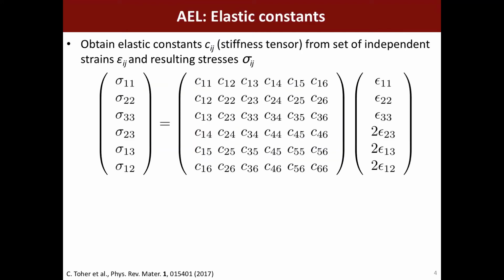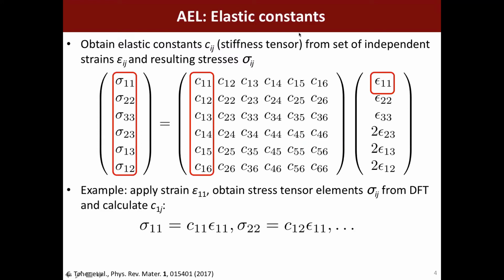Okay, so then for these different strain structures, we do a DFT calculation and we get the stress tensor. So these are essentially a set of pressures on each of the faces in each different direction. So we apply one strain. Here's an example. So this is a strain in the 100 direction of the cell. Then you'll have a stress tensor. So you'll have the stresses along each direction. So these are the normal stresses, and these are the shear stresses.